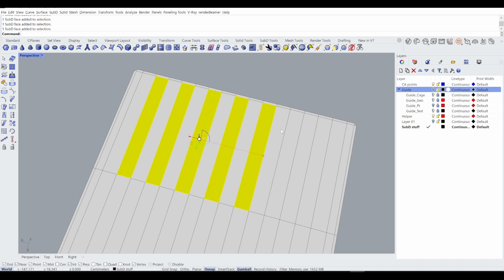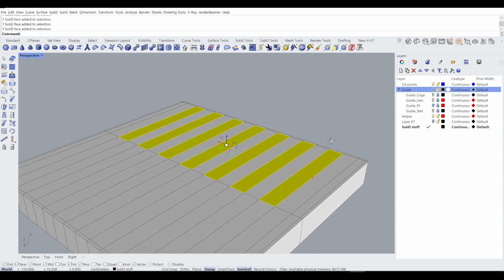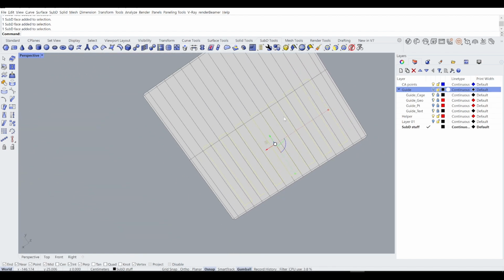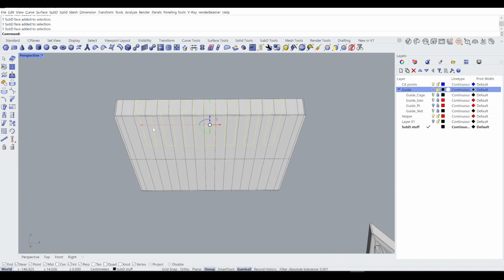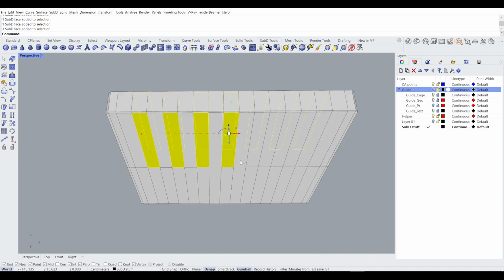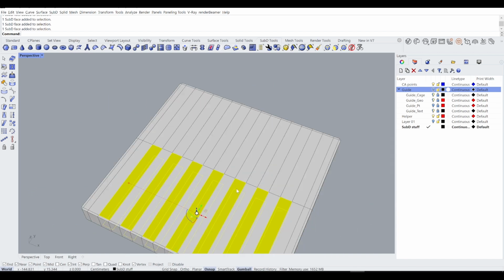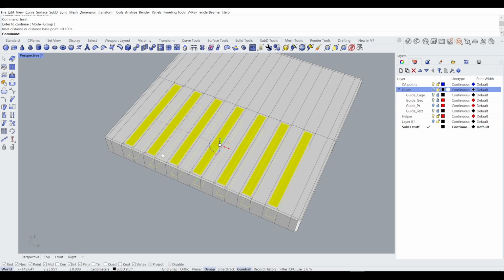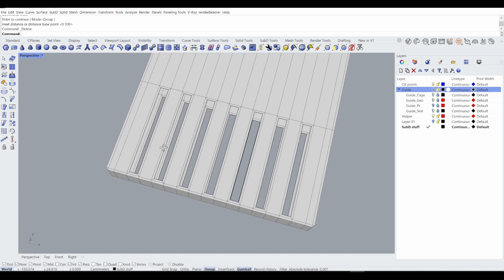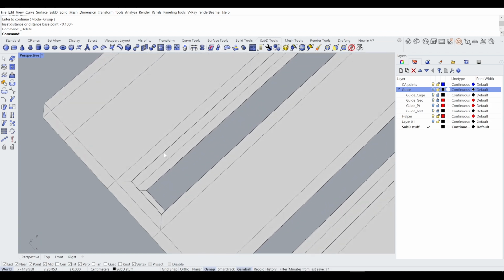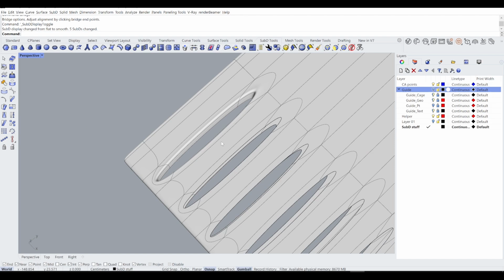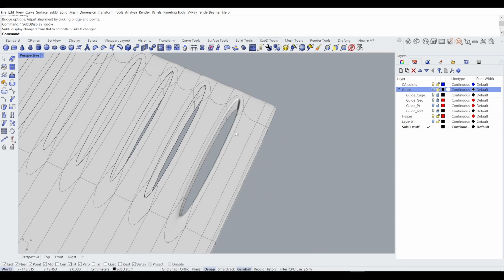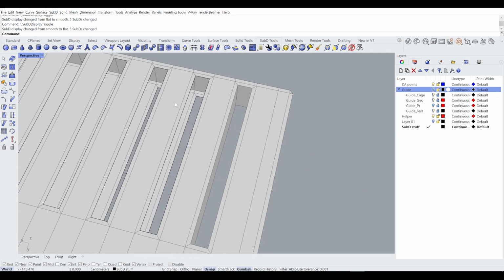I will be creating holes, but I wanted the holes to be protected. So the idea is that I will be selecting the surfaces in the top and in the bottom. Control Shift, by the way, if you don't know how to select them. I will inset them by the same magical number of 0.1, and then I will delete them. So now my holes are going to be protected, which means that if I bridge them and hit Tab, you can see how much sharper this thing gets, right? And that's what we want. We want the holes to be a little bit sharper.